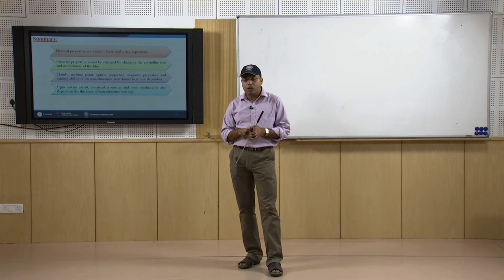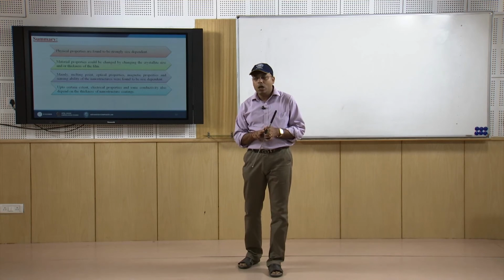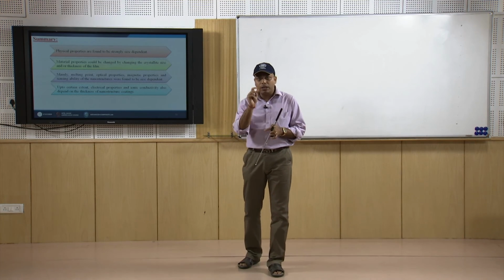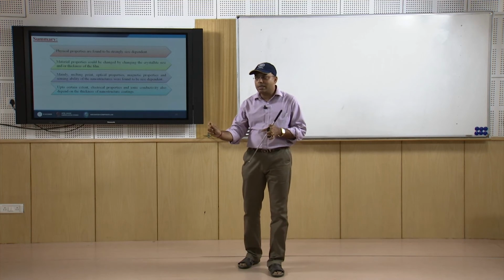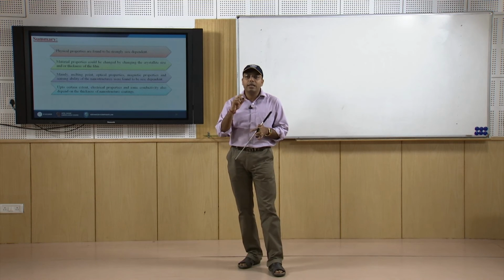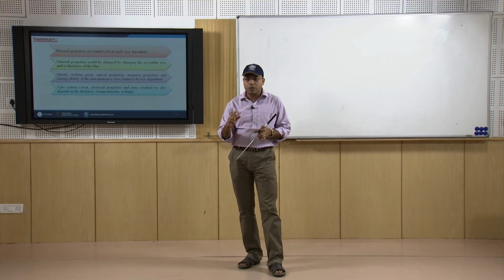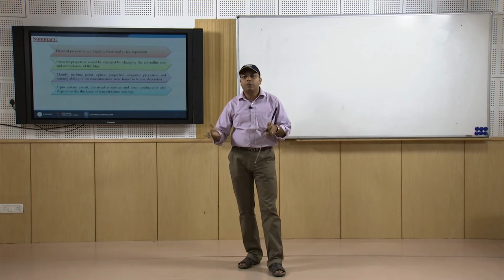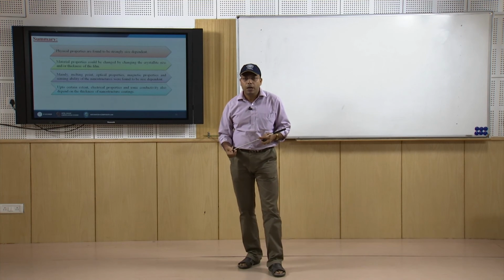One is the particle size, or grain size, or crystallite size of the nanoparticles used for making the nanocomposites, and second is the thickness of the nanocomposites, because if the thickness is more, the loading of nanoparticles will be more, thus resulting in good properties.